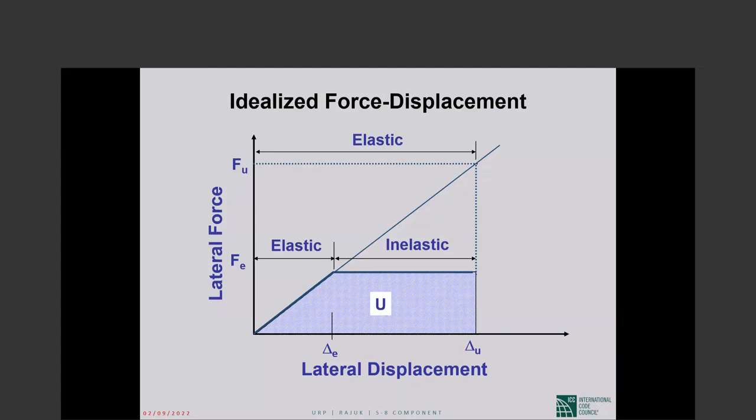The inelastic deformation capacity comes from proper detailing of the members and the joints. So we are now in the detailing part. The whole idea behind detailing is that if we choose this low strength level, much of the deformation suffered by the structure in the design earthquake will be inelastic deformation.